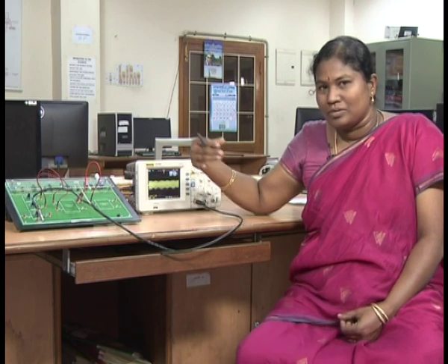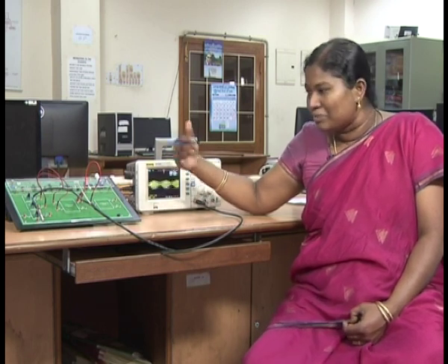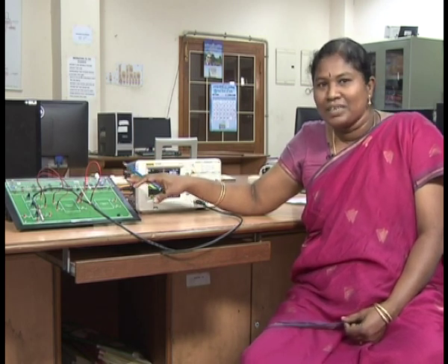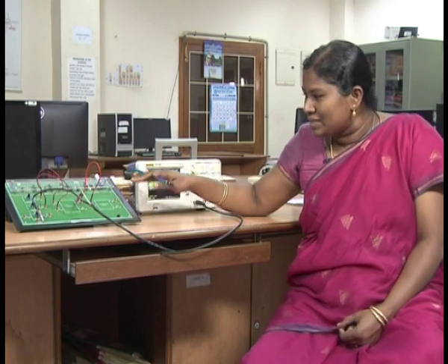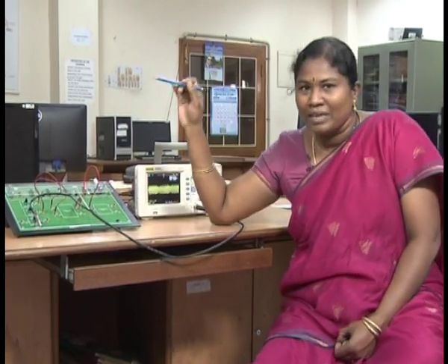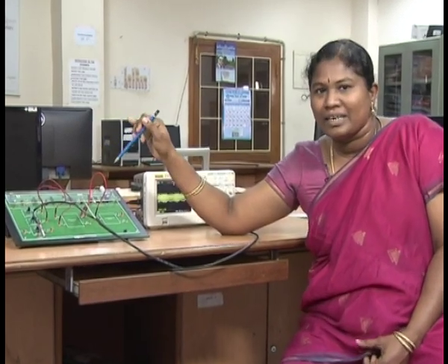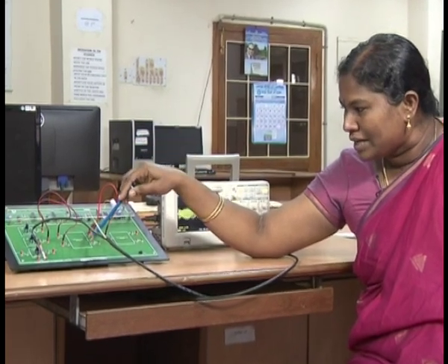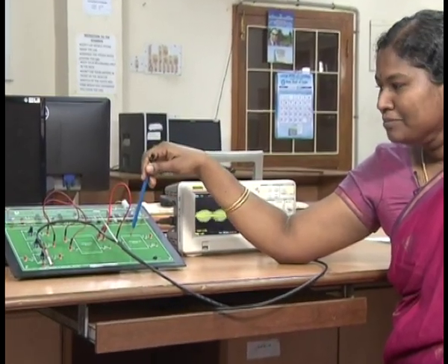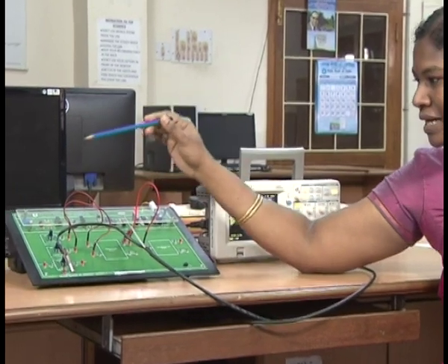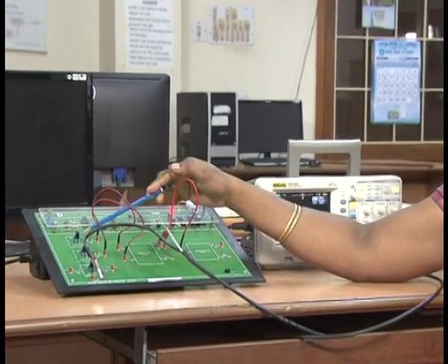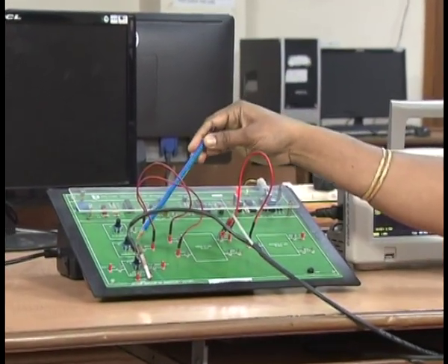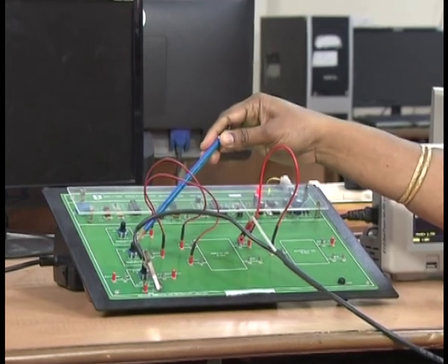In order to have more comfortable learning over the communication part, we can generate the same thing using kits. These are commercially available at many places. This is one such kit where we will not be troubleshooting with respect to electronics, we can directly go with the parts learning with communication. We have an AM modulator block here and an AM demodulator block here. To the AM modulator, we will be providing the message signal whose amplitude can be adjusted using this knob, and the carrier signal, whose amplitude can be adjusted using this knob.